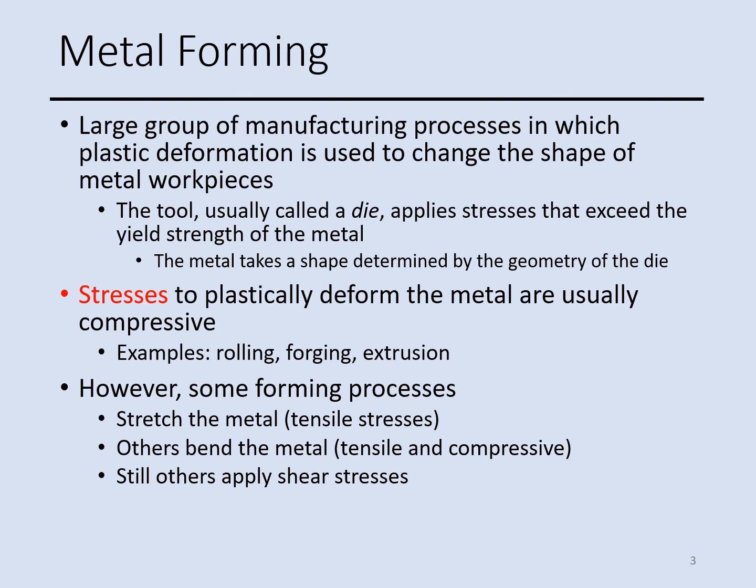And what is the yield strength? The yield strength is the stress that a material can withstand without permanent deformation. Let me give you this example. Here we have a stress-strain plot. This is stress, this is strain. Okay, and then we have a dog bone sample. Then we pull apart the two ends of this dog bone sample.